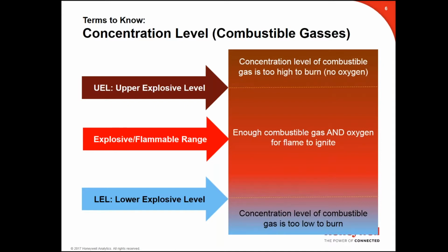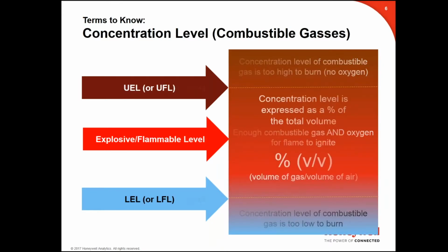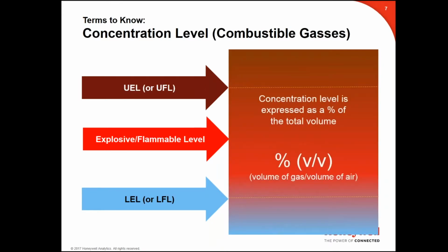It's worth noting that some refer to these upper and lower flammable limits as UFL and LFL. So UFL is synonymous with UEL, and likewise LFL is synonymous with LEL. Gas concentration is expressed either as a percentage by volume or a percent LEL. For example, 100% LEL methane is equivalent to 5% by volume in air.